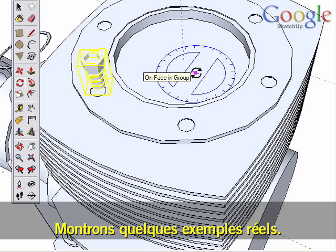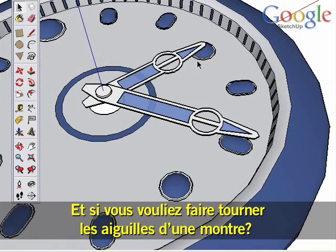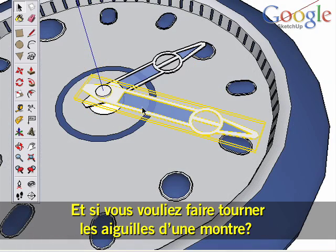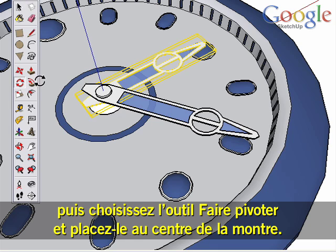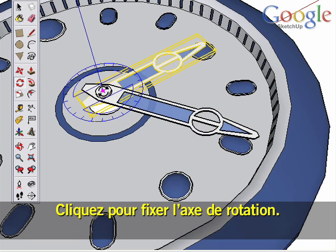Now, let's show some real examples. What if you wanted to rotate the different hands of a clock? Select the hand you want to rotate first, then choose the Rotate tool and move it to the center of the clock. Click here to set the rotation center.